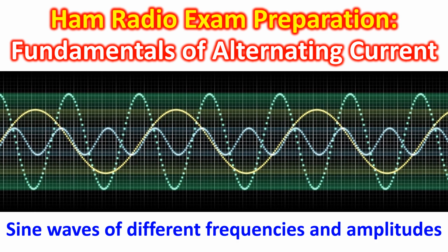If the instantaneous values of current and voltage are plotted on a graph against time elapsed, it is seen as a sinusoidal or sine wave pattern. Sine waveform is used in power transmission because that leads to the most efficient transmission of energy. Inexpensive power inverters for converting direct current to alternating current may use square waves.